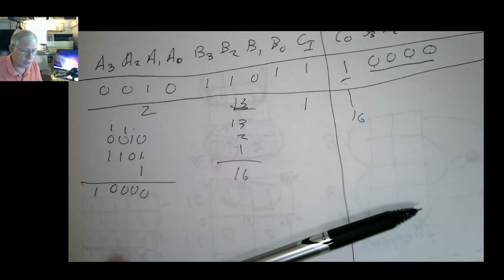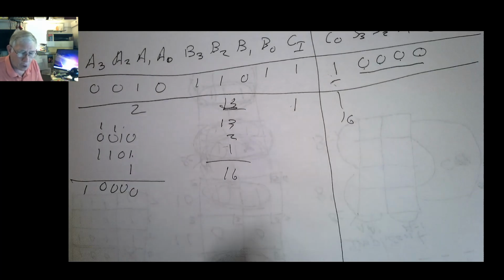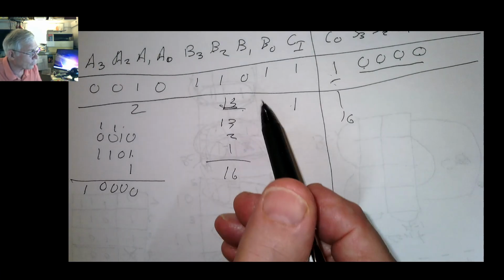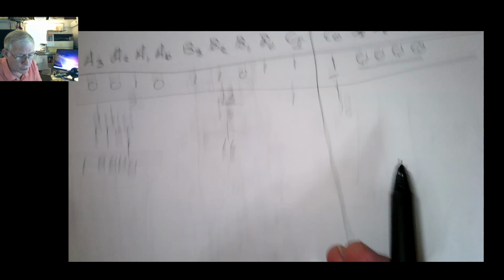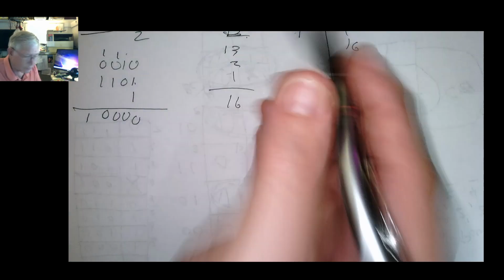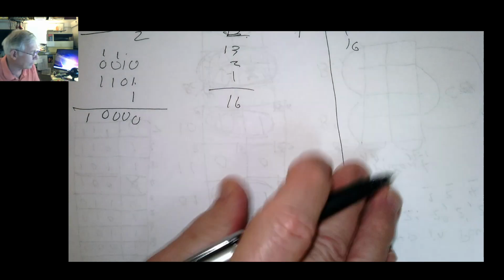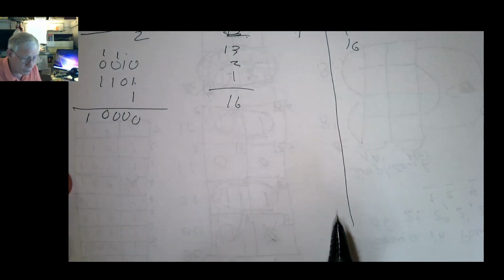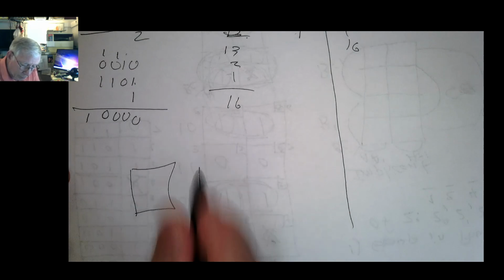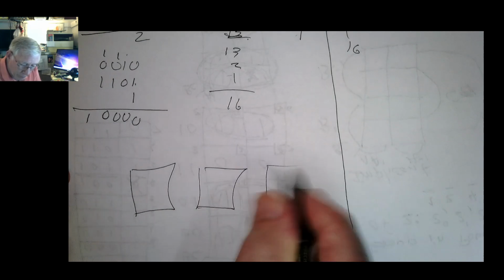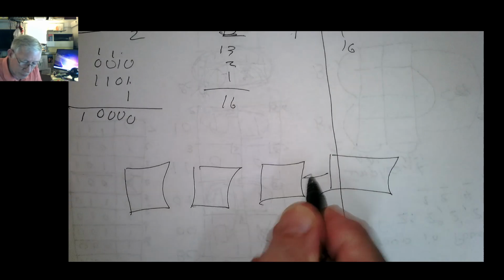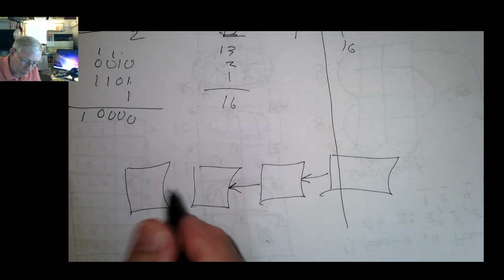And of course, now think how difficult this is going to be. So in order to simplify this design, we don't have 9 independent variables and use that to do our design, because that would just be a huge mess. What we do instead is we take 1, 2, 3, 4 1-bit adders, and we daisy chain the carry outs.